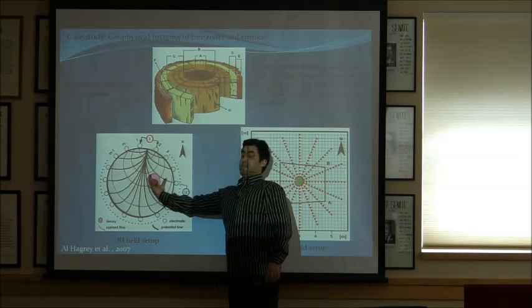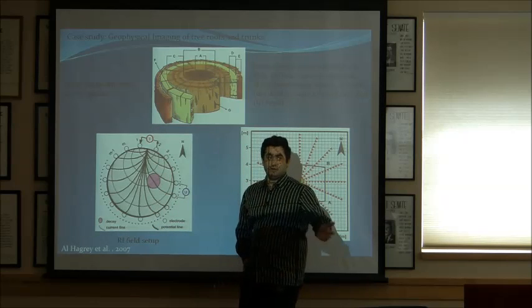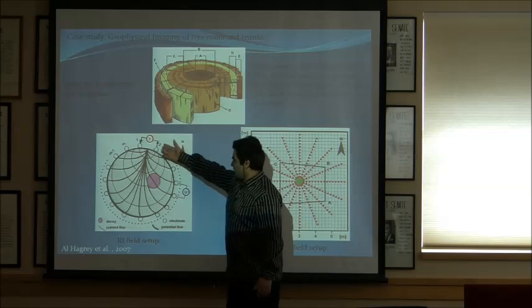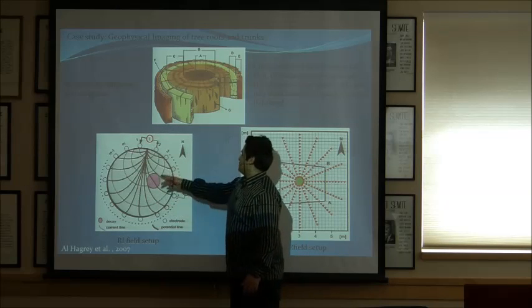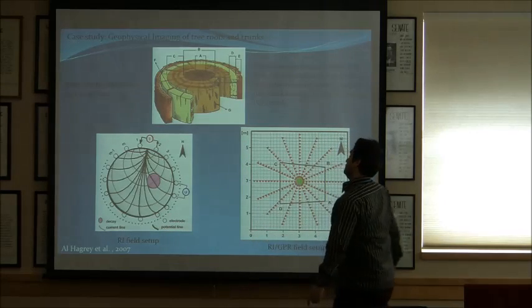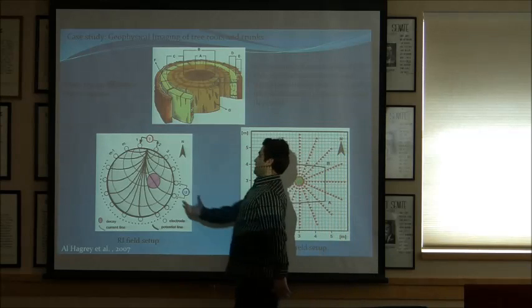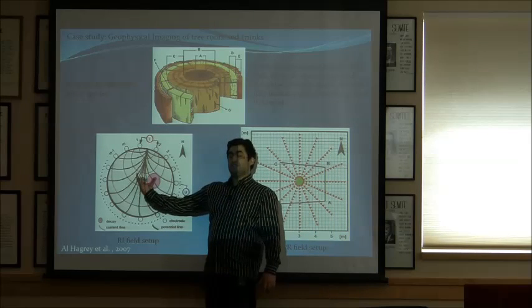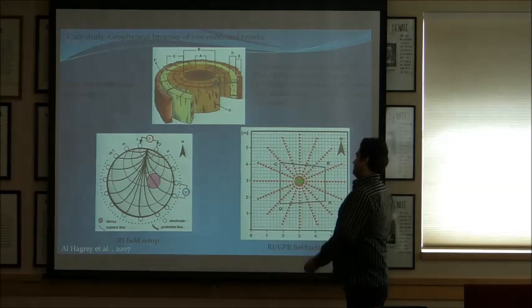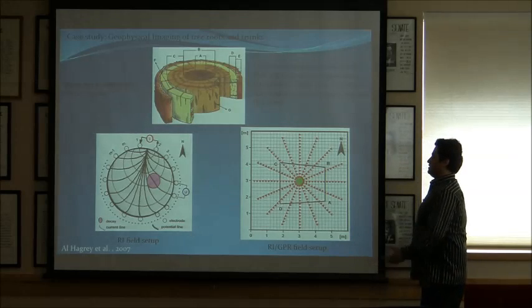You have here assumed decay, any sort of disease or bacteria that the tree has. And here you again plant the electrodes around. The number of electrodes depends on the diameter of the tree you have. And you take the measurements and invert the data. Hopefully, if you get high resistivity at the center, that tells you this tree is good. If you get low resistivity, that basically, in general, means the tree is bad.